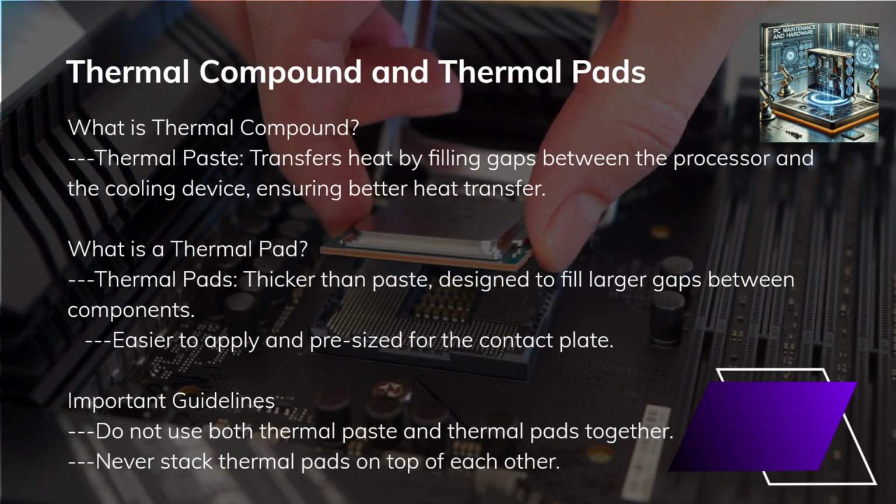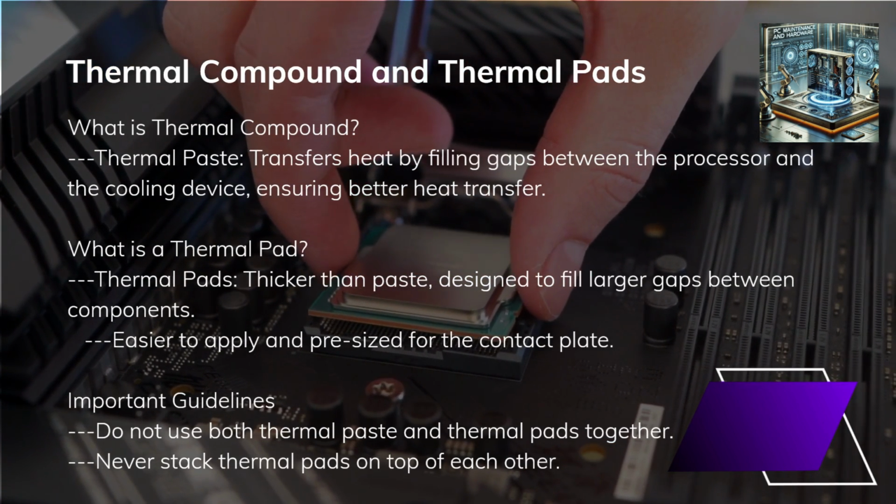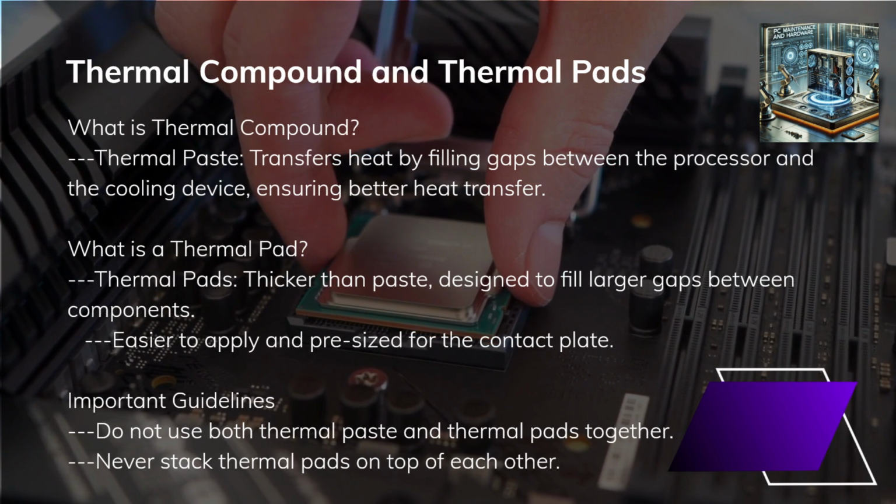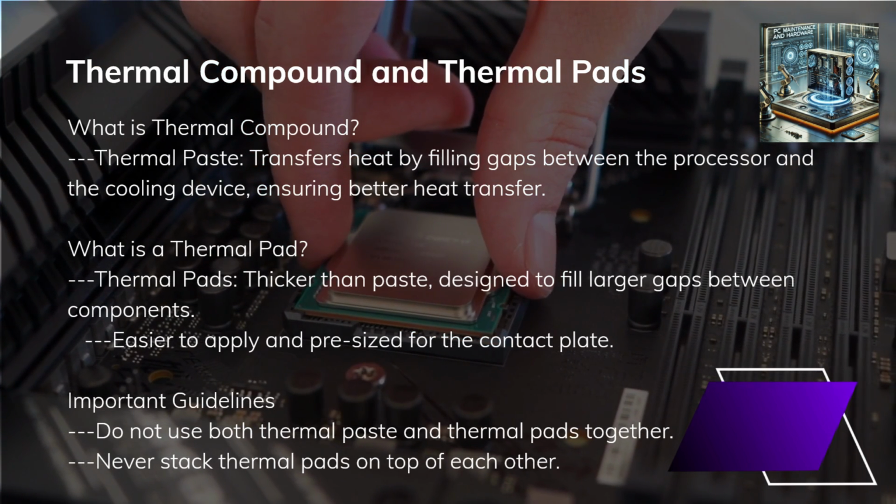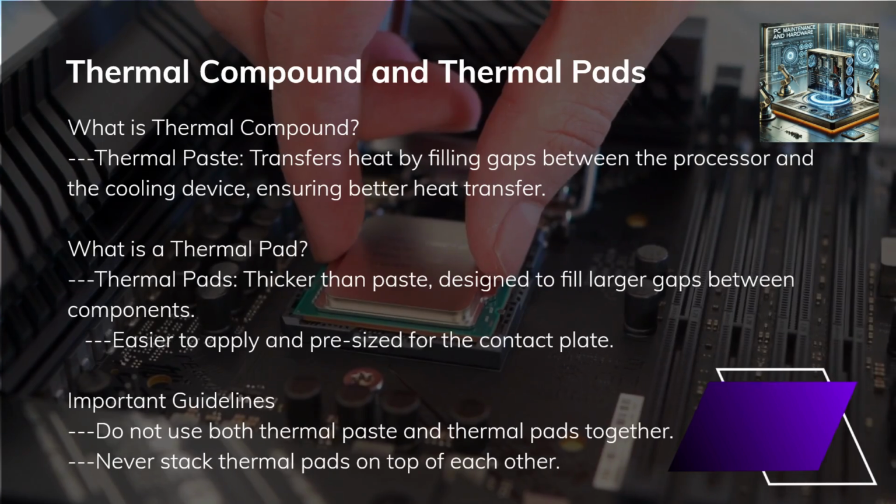However, a few important rules: never use thermal compound and a thermal pad at the same time, and never stack thermal pads on top of each other. Doing so can prevent proper cooling and damage your system.